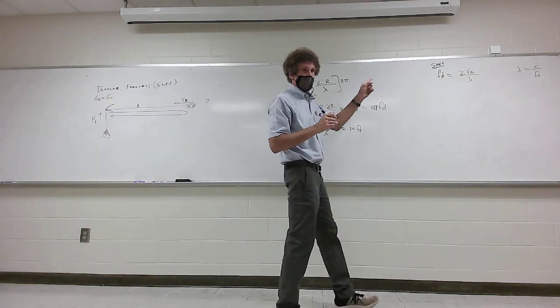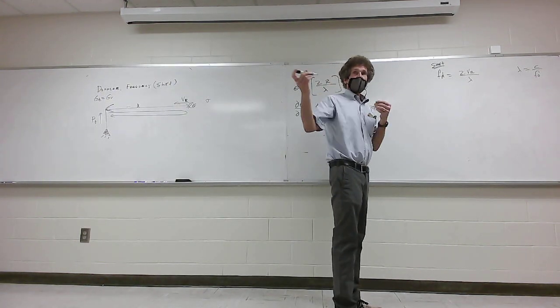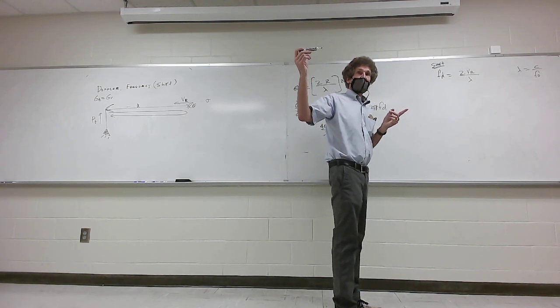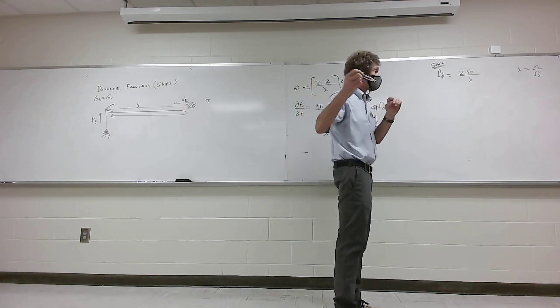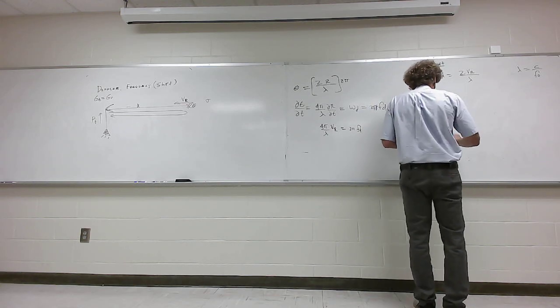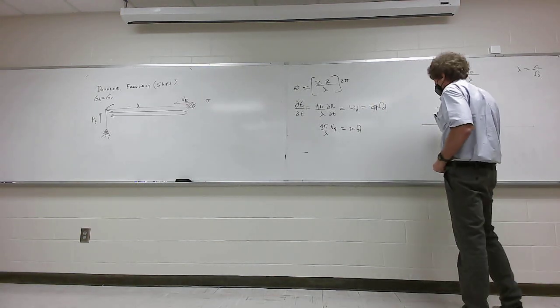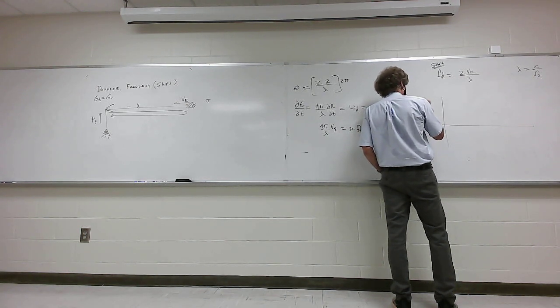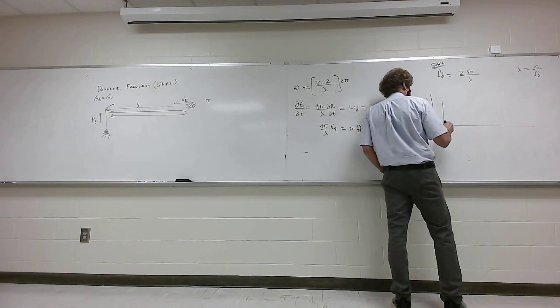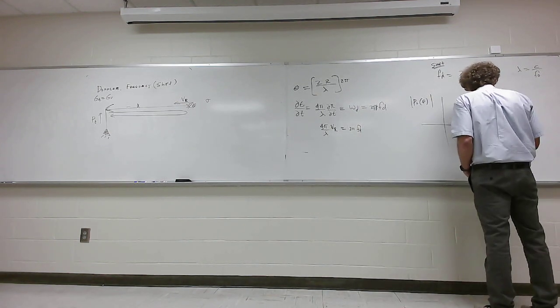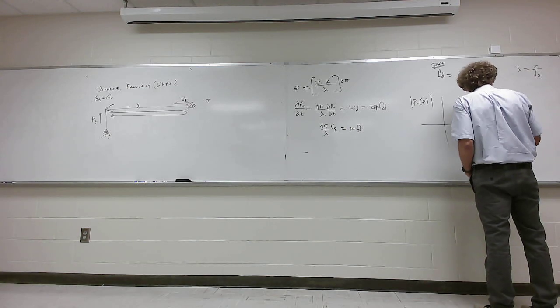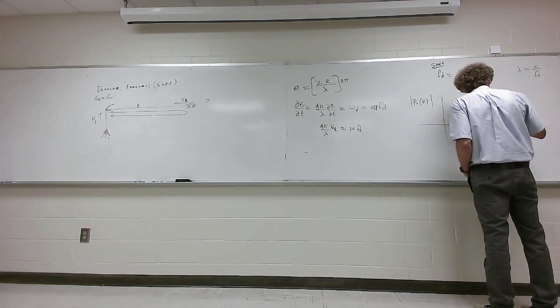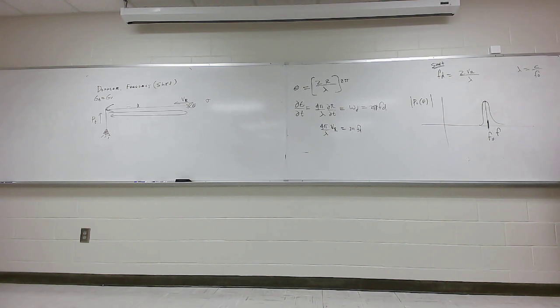Now that Doppler shift, here's the thing. If you're approaching a target, the Doppler shift is going to shift the center frequency. And here's really what happens. You don't have to write this down, but if you looked in the spectral domain and you look at the magnitude of the power received versus F, you're going to see at the transmit frequency something like this. There's going to be very, very little width there. You all with me on this?